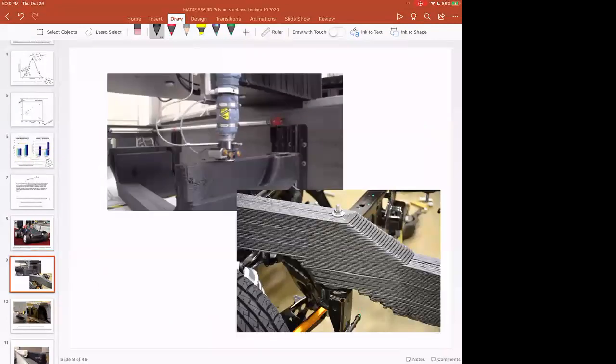So again, as you're printing big stuff, there can be big defects, and so you can get geometric defects. You see some problems here with this sort of overhang. You see issues here where they're not getting perfect extrusion, and so it's really hard to go back and fix those or really hard to correct those on the fly. So you'd like to have a well-tuned process where you don't have to deal with this and you're throwing away hundreds of pounds of composite plastic.